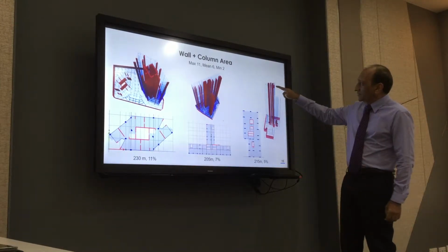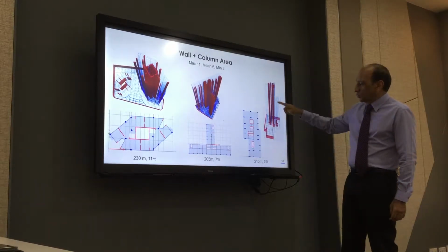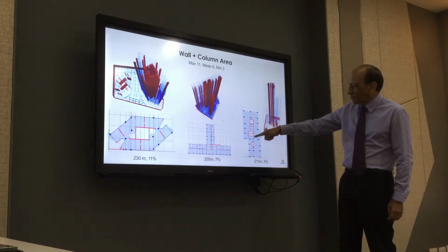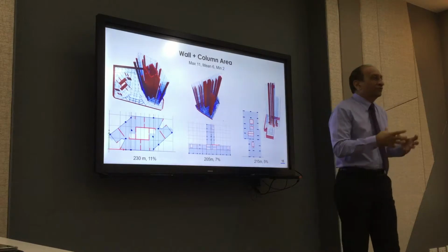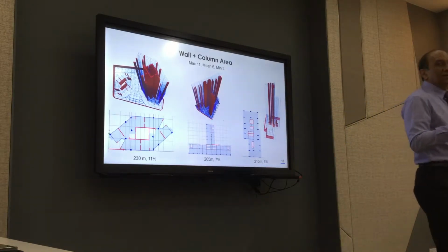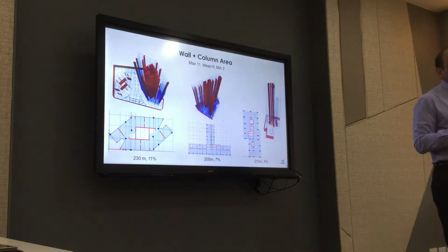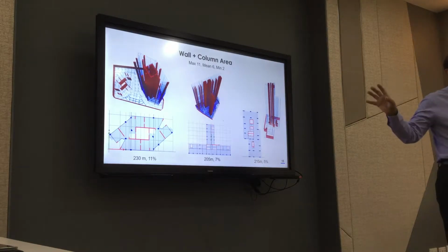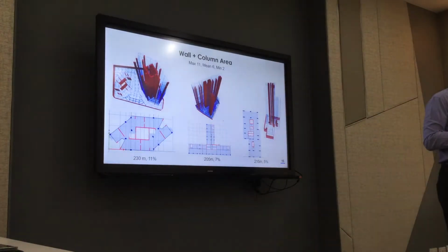And one of the reasons is they put an outrigger over there. Those are not linked together. So these are also linked by beams. So they try to improve the structural performance by coupling things together. And you can see the effect on the area, right?